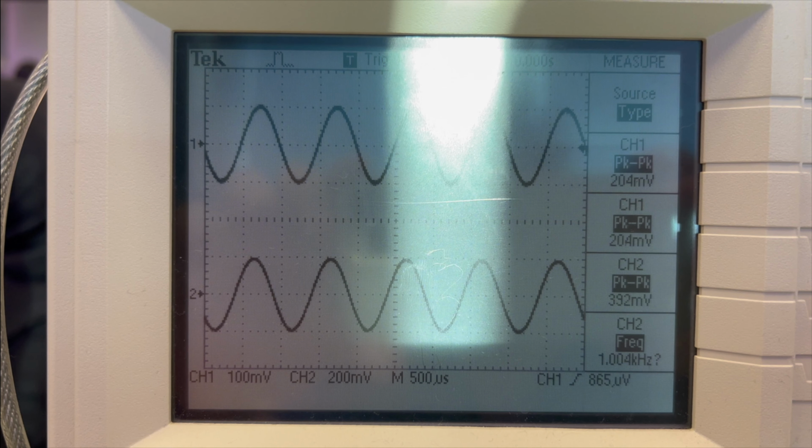As the single supply mode causes the negative side of the waveform to be cut, the level shifter, also known as the voltage divider, will shift the entire waveform up, ensuring no waveform is cut. To set up stage 1, the power supply is set at 9 volts and is connected to the circuit.